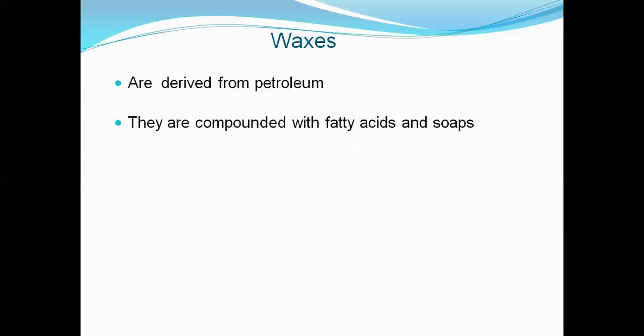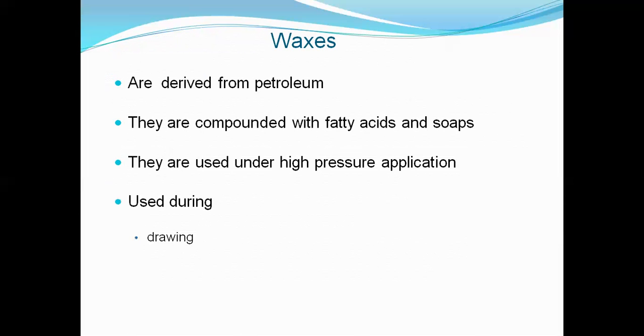And the last one: waxes are derived from petroleum. They are compounded with fatty acids and soaps. They are used under high pressure applications, such as during drawing, rolling and extrusion operations. So those are the types of lubricants.